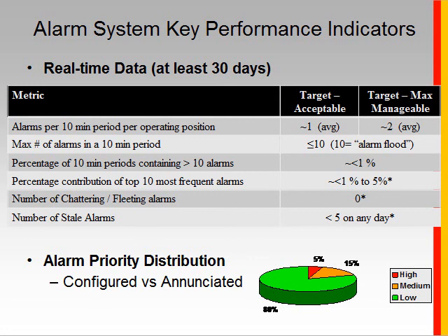And you want to work with the system to make sure that for alarm floods, you're minimizing the amount of time that the system is in flood condition, and you're minimizing the number of alarms that are presented to the operator during the flood. So at Milford Haven, the operator probably would have had a much better chance of responding correctly if during the upset or the flood he was presented with 12 alarms instead of 275. So the idea of making it as manageable as possible is really important.